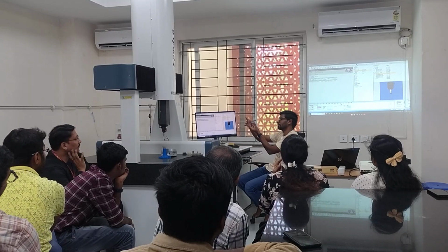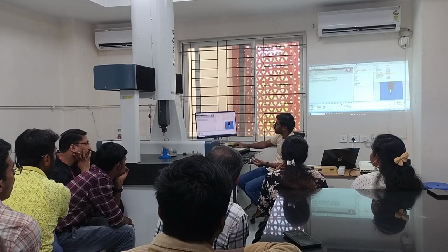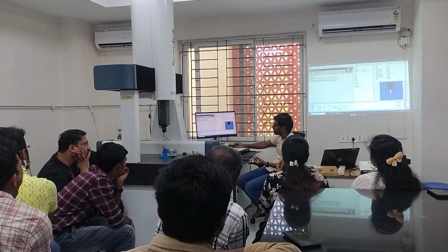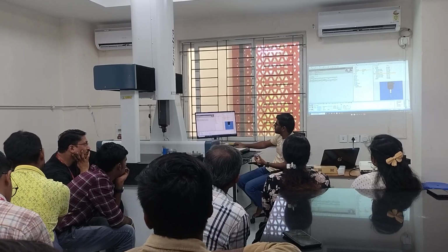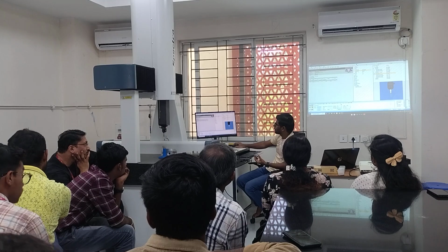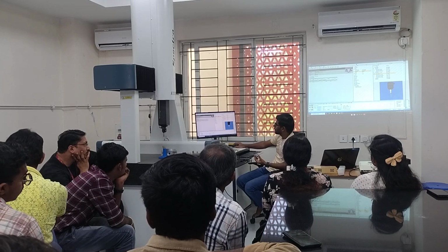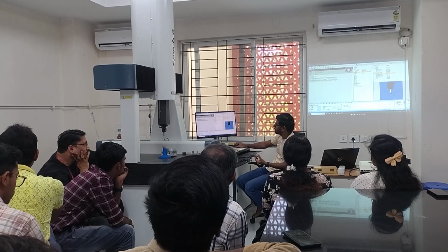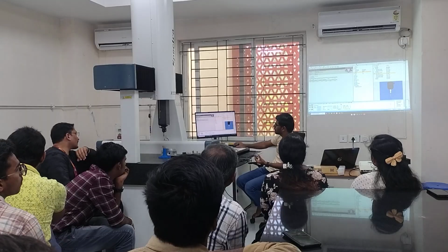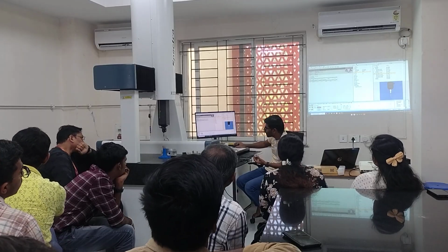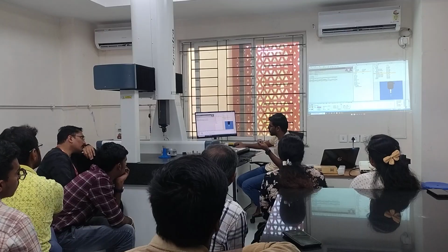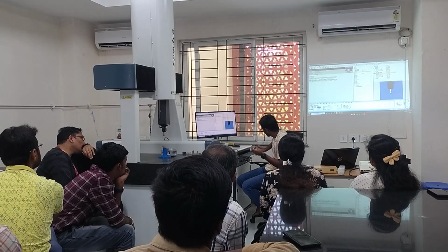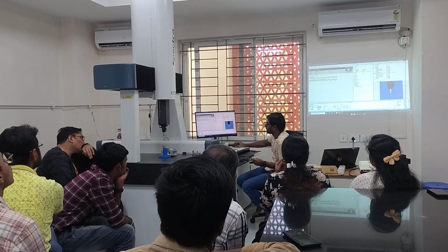Again, I'll try to find the distance between the two planes. I'll go to this distance, then again for distance, we need two features. I'll go to the right plane, I'll drag it here, then I'll take plane 1, I'll drag it here. So distance, I think I have given as 40. Okay, so nominal is 40.